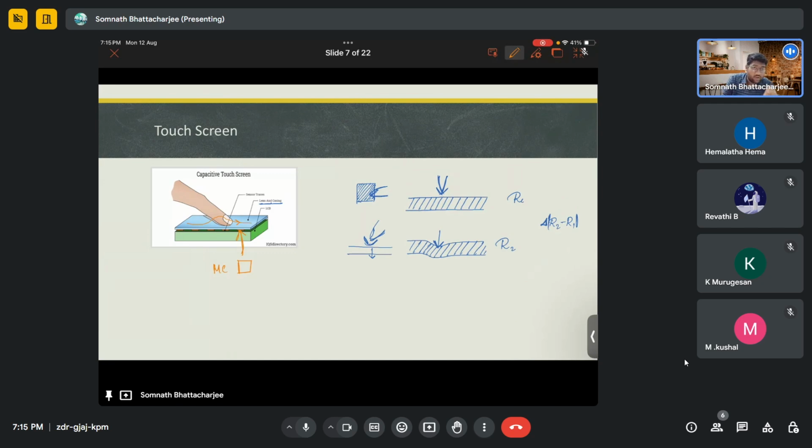And we can also know the location specifically, because there is a huge difference between a resistive touch sensor and a capacitive touch sensor. If we say the capacitive touch sensor is like this, we can divide it into 9 grids. If we press here, the response will be recorded here. If we press here, the response will be recorded here only. As we are not just pressing on it, we just touch it, that's it.